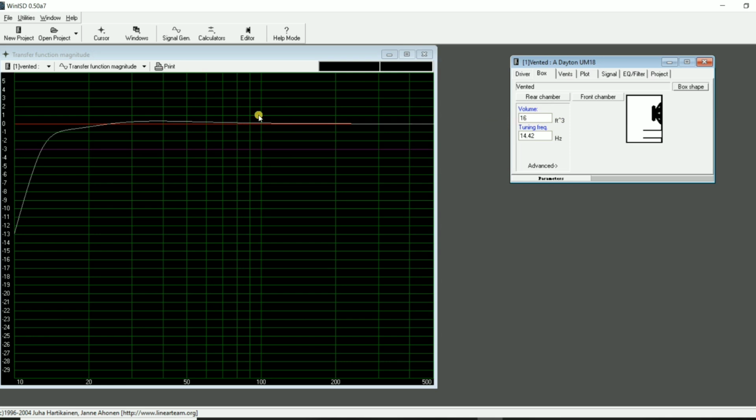Now, let's look at this response right here. We can click on the tile, and then our line is going to follow that white line, or the response that we're working with. And you see where our white line is at 26.56 hertz, and we've got 0.118 dB. That means it's slightly above baseline. And you see baseline here is the red line.